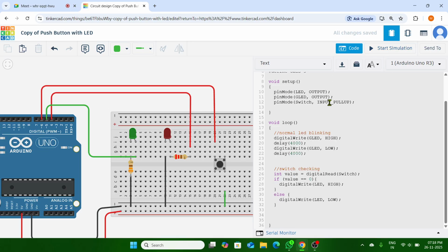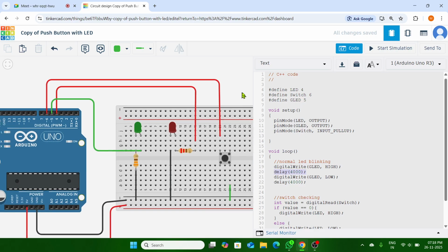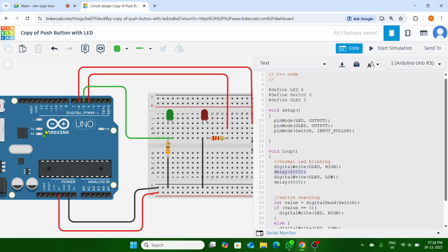Okay. So how to create that? I will explain that. You understand that delay concept, right? The CPU is completely freezing here. It is not even coming here, or even after it comes, it suddenly goes to the delay and just freezes on this delay. So that's why we need to create a non-blocking delay using a timer. Okay, the timer is what we are going to work on in this class. In Arduino or ESP, whenever we are programming, there is something called the millis function.